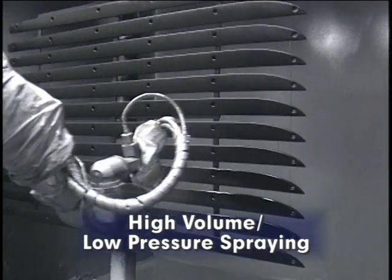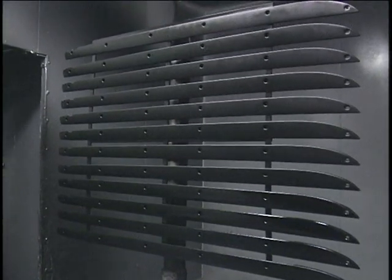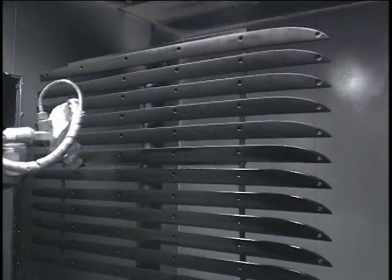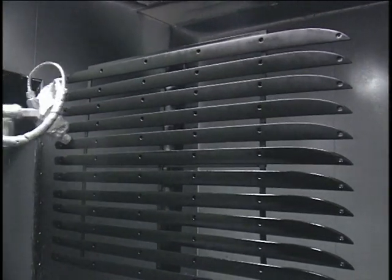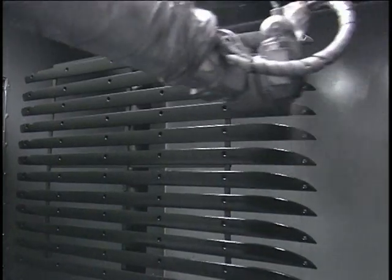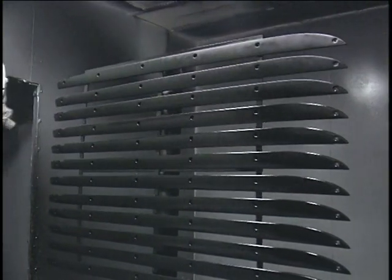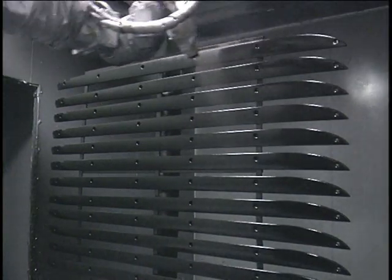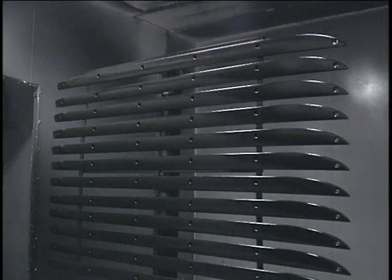High-volume, low-pressure, or HVLP spraying is an air atomization system that uses less than 10 psi, or 69 kilopascals, of air pressure to apply paint. HVLP spraying produces a softer, more controllable spray, reducing overspray and paint wastage.